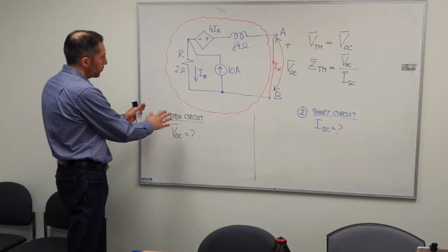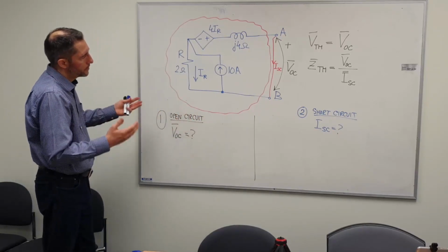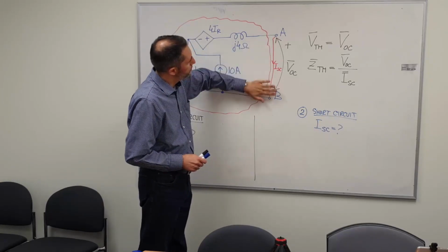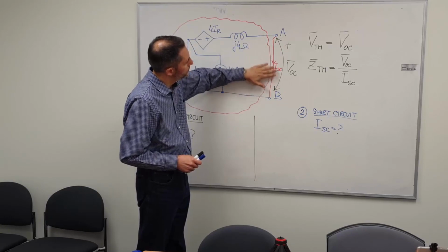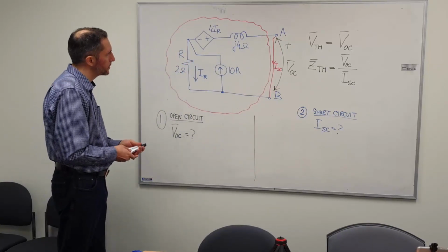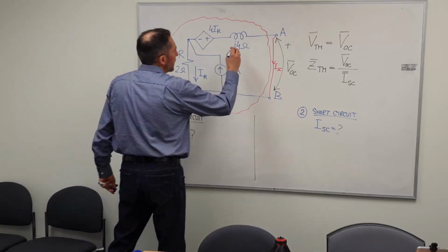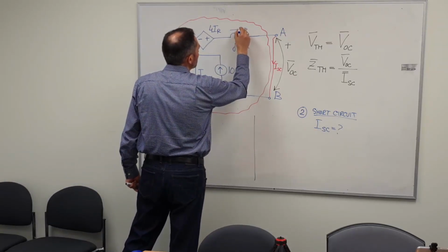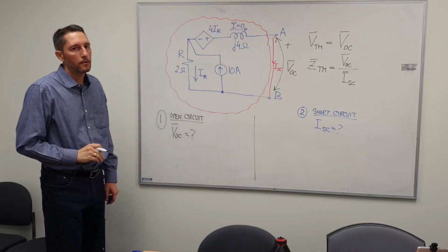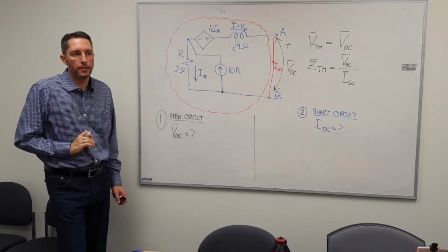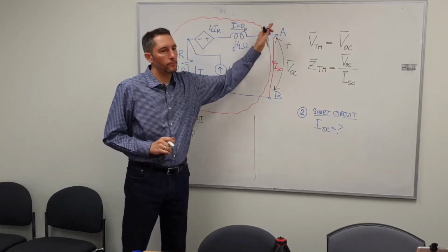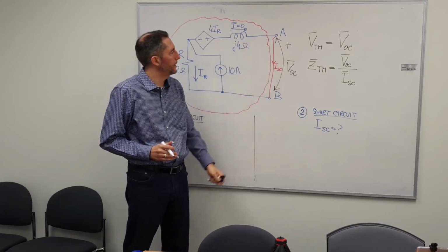So let's now focus on circuit 1. In circuit 1, these two are open, therefore this short doesn't exist. If that short doesn't exist, then we can say that the current that flows through this inductor must be 0. Is this clear? Yeah. Because if there would be some current, there would be nowhere for that current to go. It's simply a dead end.